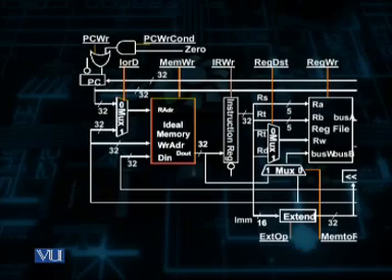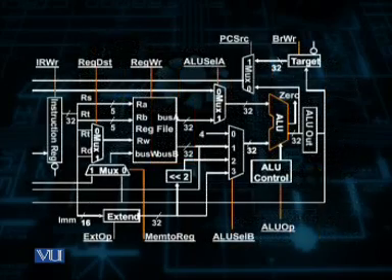Here the function of clock cycle 2 is shown. You can see that firstly, the instruction is decoded. The RS, RT, RD, and immediate 16-bit fields of the instruction word are made available on the respective lines. Secondly, the registers at RS and RT are read at buses A and B respectively, and they are stored in the temporary registers A and B.